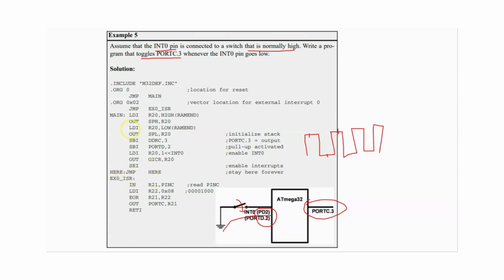So that is why normally in this code, we see that this command, which is labeled here, is the line where the controller is idle. It does nothing, and it stays here. Whenever this interrupt occurs, that is, the pin is pressed to low, then it serves the interrupt. As we discussed, every interrupt has a special allocation.